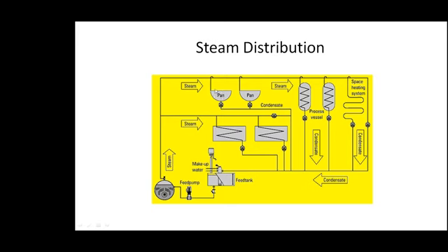How the heat transfer takes place: there's a cold solution inside, steam is coming, immediately steam condenses and transfers the heat to the solution inside. So the steam condenses, gives up its latent heat and becomes water, or condensate as it is called. The condensate comes out, steam is continuously supplied, solution is continuously poured in, and we draw out the condensate.